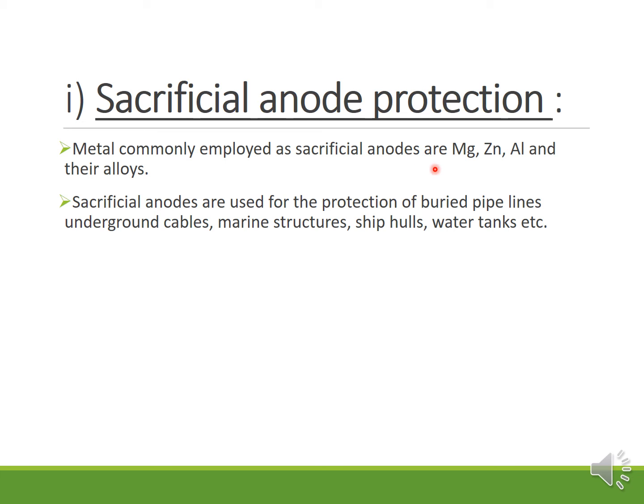We are using reactive metals like magnesium, zinc, aluminium and their alloys as sacrificial anodes. This method is used for protection of underground buried pipelines, underground cables, marine structures, ship hulls and water tanks to prevent them from corrosion.